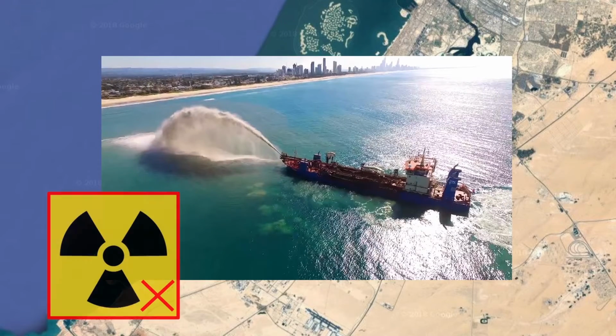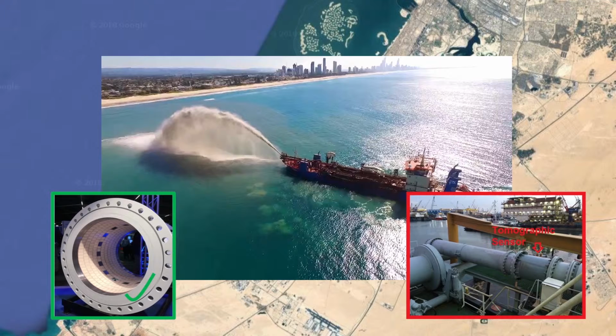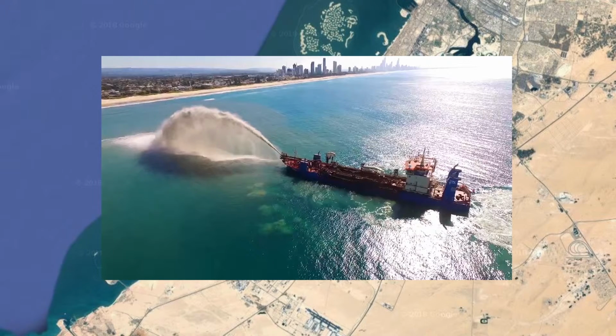In the past, density sensors have exploited a radioactive gamma ray source. These have major safety issues, need periodic replacement, and can cause long delays for certification as the ships move between countries. Companies are replacing their gamma sensing units with electrical tomography sensors to eliminate these problems. The non-intrusive sensor is simply inserted into the slurry feed pipe. Control of the raw material flow is essential to provide optimal effectiveness and efficiency.